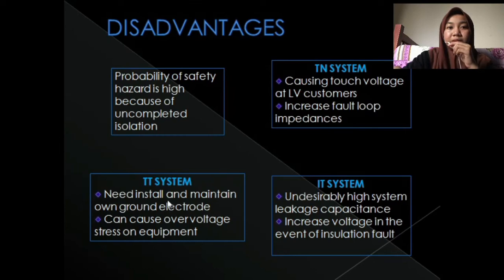For the TT system, it needs to install and maintain a ground electrode, so the reliability is not assured. Next, high overvoltage may occur between all live parts and the protective conductor, which can cause overvoltage stress on equipment insulation after installation.